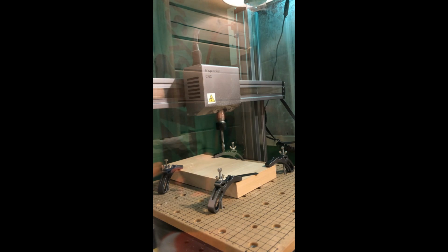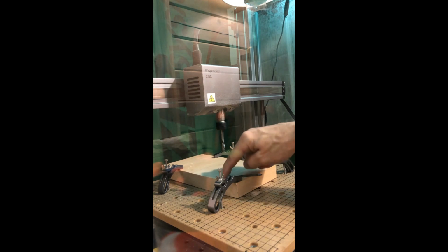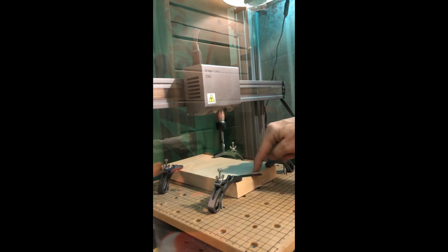So I set my 0 points right here, even though it's up in the air, because it doesn't matter yet, just as long as all your zeros are right here. That way, when you go to set the point where the top of your wood is, you still have your 0 point set over here, because all we have to do is change the Z over here. So, this is what we'll do.